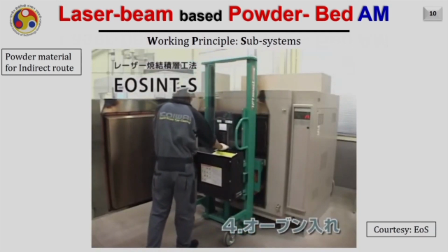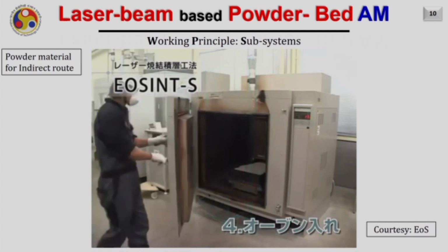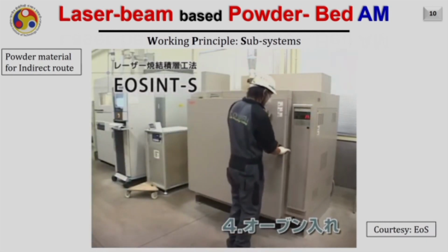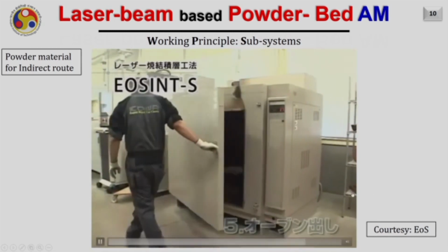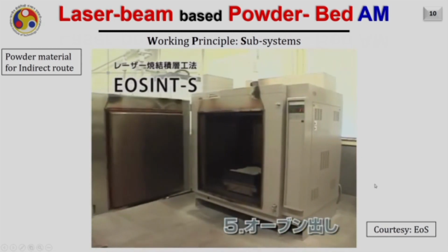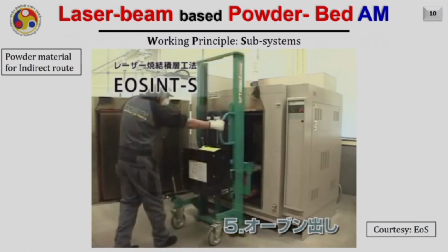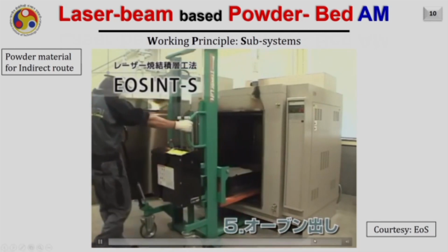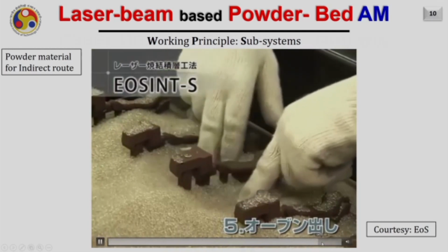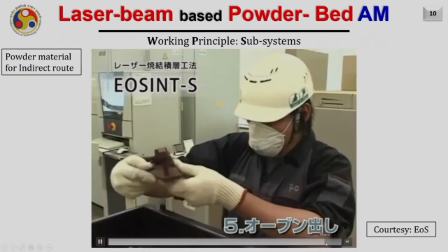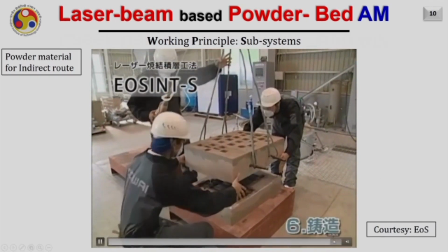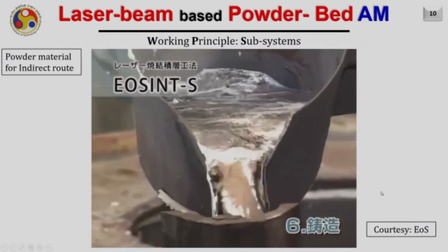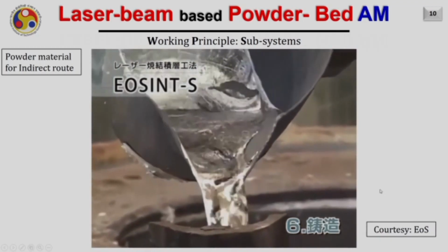the entire mold is kept in the furnace where the binders are going to be removed. After this stage, the parts which we will have here will have very low strength. Subsequently, at the same time, the infiltrated material rises under the capillary effect and fills these pores. As a result, we have a very strong part produced by this method. And it can be noticed that it is nothing but a direct sand mold. Now one can directly pour the material into it and get the part created.